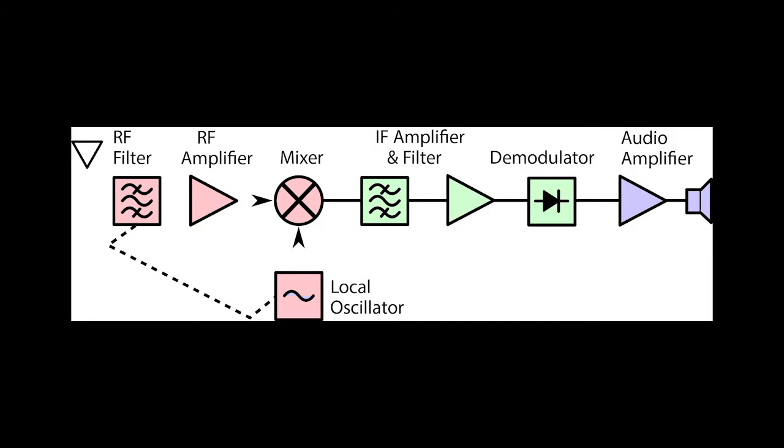Assuming we all are well equipped with the basics of electromagnetic waves, we introduce you to a very basic block diagram of a simple radio circuit. First, we have an antenna. Electromagnetic waves after transmission at the receiving end vibrate the free electrons present in the conductor, that is the receiving antenna. These vibrations produce an electric field which regenerates the transmitted signal and passes it to the RF amplifier.